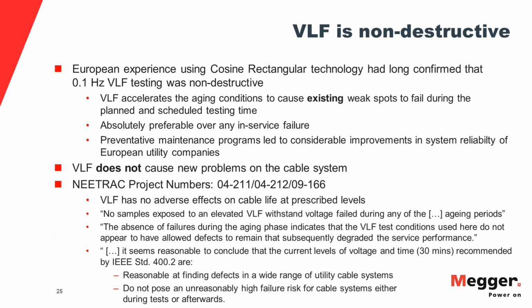And then one of the biggest things is pretty much that some people would always consider VLF testing as a destructive test, which it is not. I repeat, VLF is not a destructive test, because there's two types of AC hypot test. There's the withstand test, and then there is the step test. The withstand test has the intention of, you apply the voltage, and it's a pass or fail test, go, no go test.